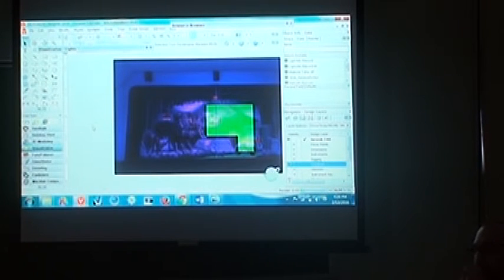If I was also creating a light plot, which I have in this file, any of the lighting symbols in my light plot in Vectorworks are also light objects. You can just click on any of those symbols, right click, edit light, and you'll get those same on, off, emitter settings and all that. So you could use the actual fixtures of your lighting plot to do the lighting render.